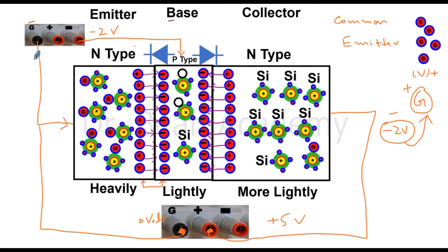It means ground is working as a positive, so this n-type side is connected with the positive terminal. And this is of course negative. So the p-type side is connected with the negative terminal. If we consider it like a p-n junction only, not a part of the transistor, then the p-type side of the p-n junction is connected with negative and the n-type side is connected with positive. This is in reverse bias mode, so no current will flow.